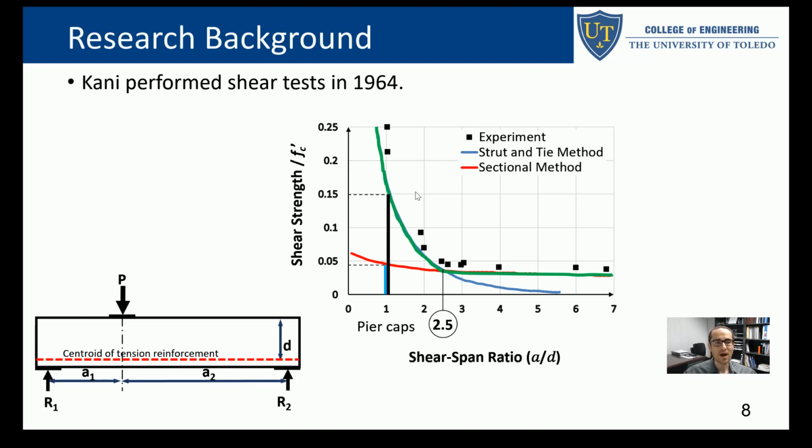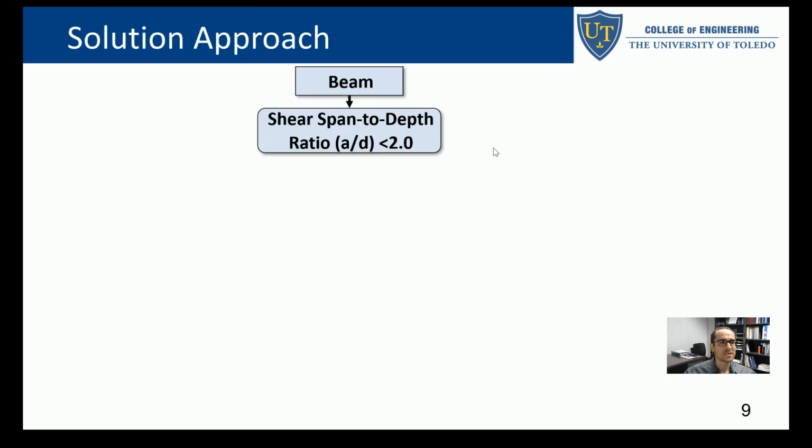We looked at how to benefit from this deep beam behavior using the strut-and-tie method, and more accurately determine capacities and more accurately identify overloaded bridges. So again, that's the ratio, the most important aspect.